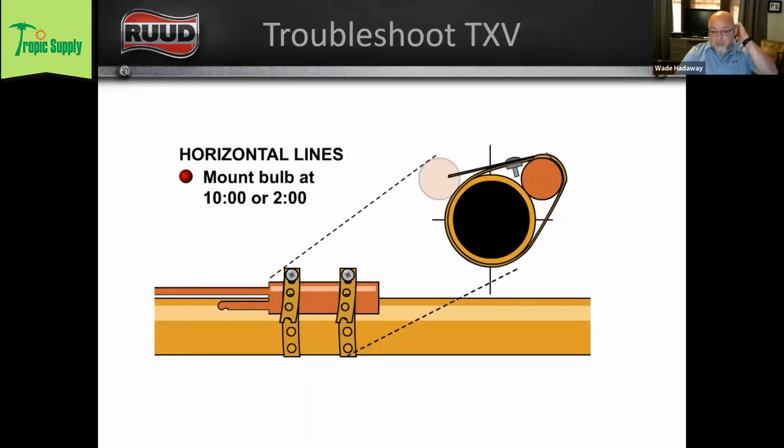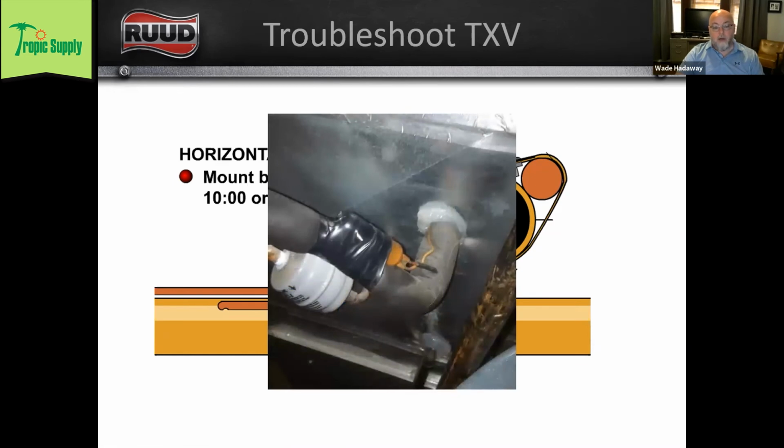It should be insulated really well. Here's a great example of how not to mount an expansion bulb or a TXV bulb.